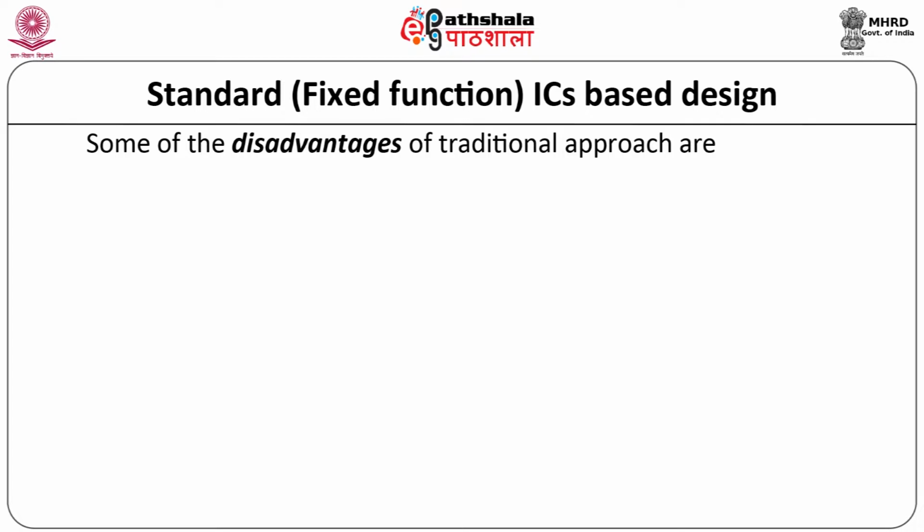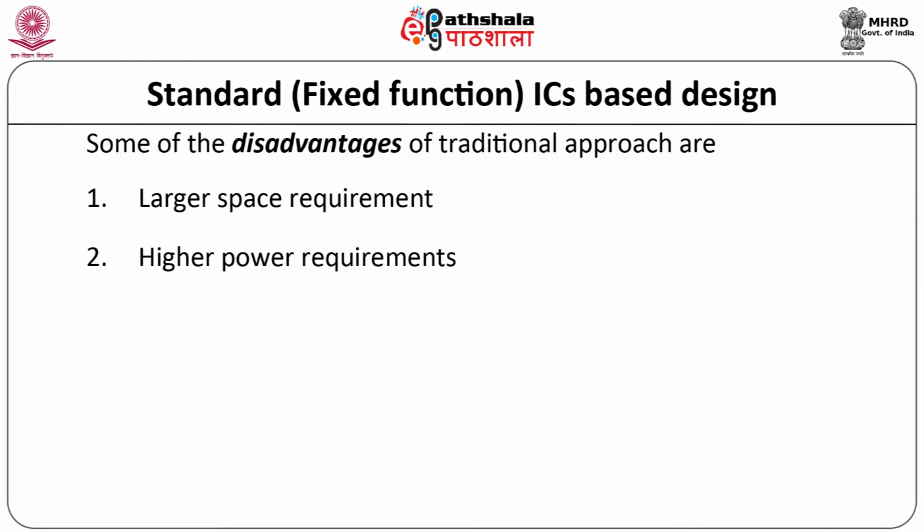Let us now study the disadvantages of the traditional approach. The first disadvantage is larger space requirement. Fixed function ICs occupy a finite space in the total board area. The second disadvantage is the higher power requirement. As there are discrete components in this design, every IC would take finite power. The total power required is the sum of the power consumption of each IC.